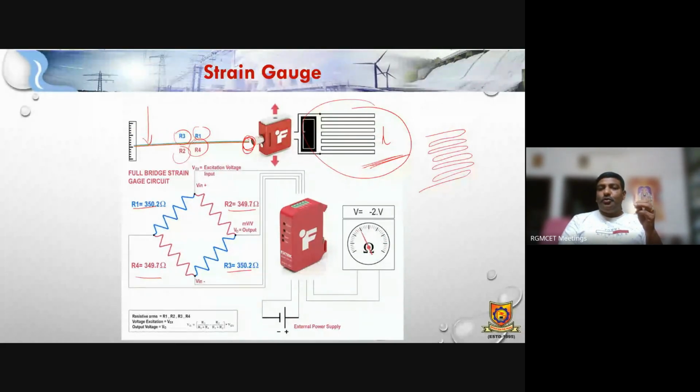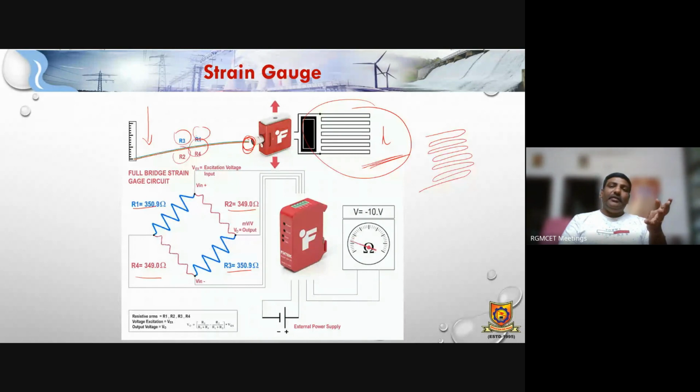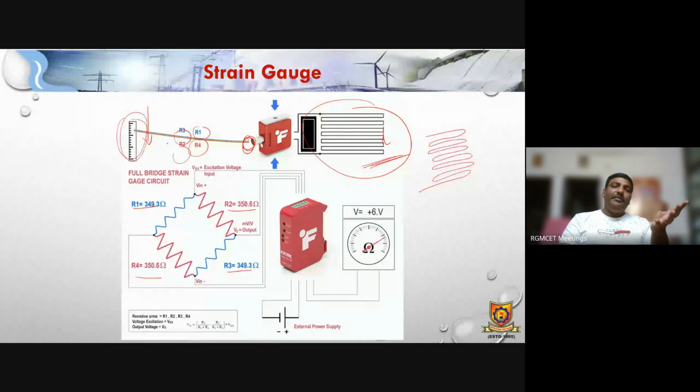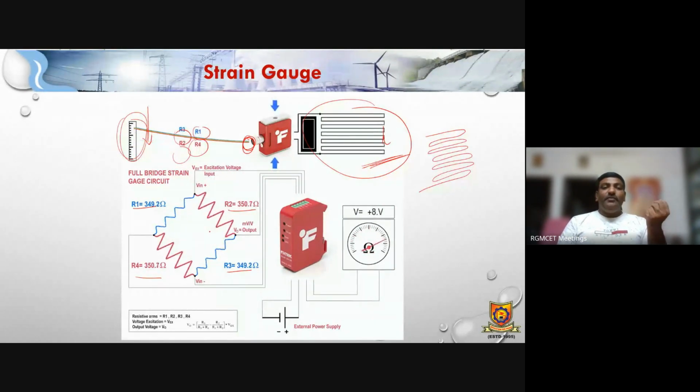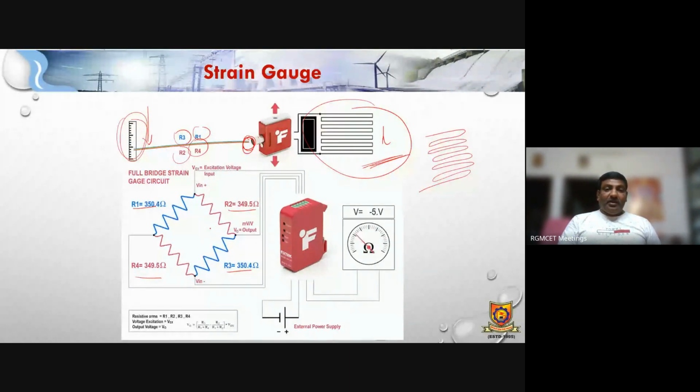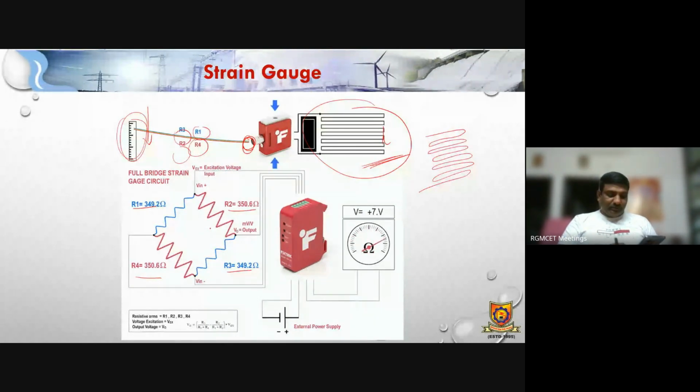These two terminals are connected here, and there is a device where we can apply a certain amount of force, and how much pressure can be applied and how much distance is covered will also be taken into consideration. We have applied these parameters to the bridge. It is a 4-arm bridge. In a 4-arm bridge, whenever it is strained, automatically the value of resistance changes.